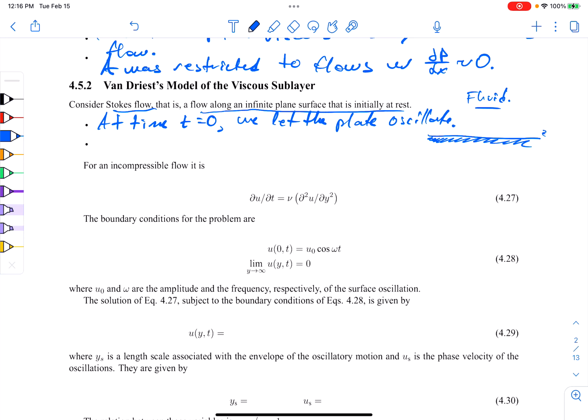I'll give you the clue that when this happens, there's basically a disturbance at the wall and shear waves develop. Because if I let this wall go back and forth in an oscillating pattern, starting at time 0, then these little shear waves are going to be coming off the wall in this direction. And in a turbulent boundary layer, there are also types of shear waves. That's why there are famous turbulence models that we'll talk about later by, say, Menter, the shear stress transport model, which is probably the workhorse CFD model in industry today. So that's sort of the motivation.